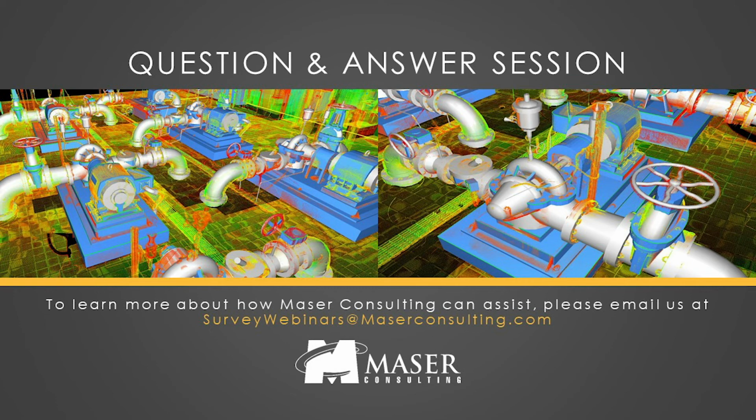And you can validate your model by cutting sections through it, by cutting floor plans and setting depths and using limit boxes and everything like that to make sure that the modeled objects are placed as they were at the scan. Alternately, there are options to do clash detection in Revit and other applications that Autodesk owns, which can tell you fairly reasonably if the model matches the scan data or vice versa.